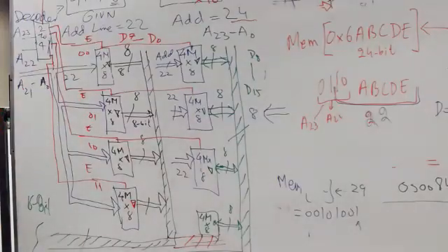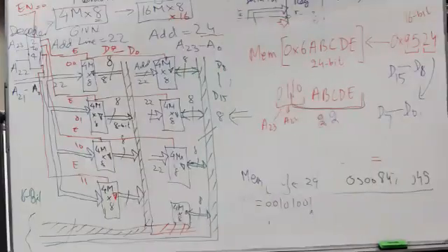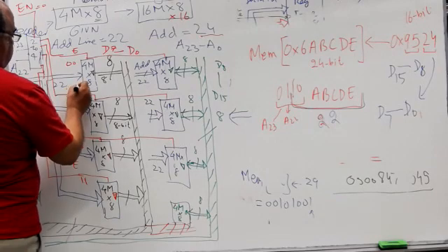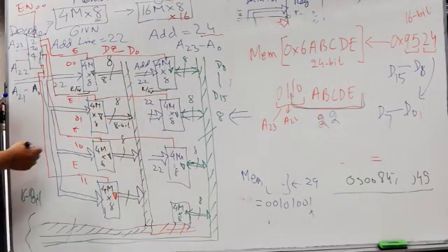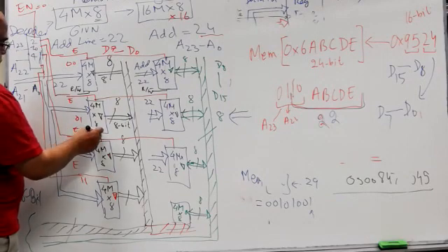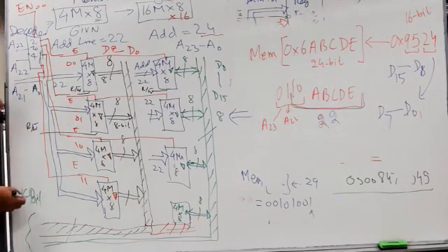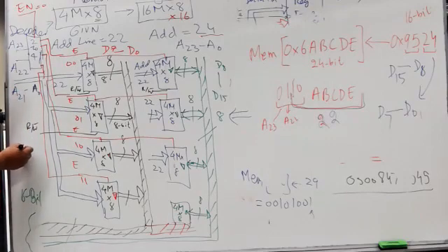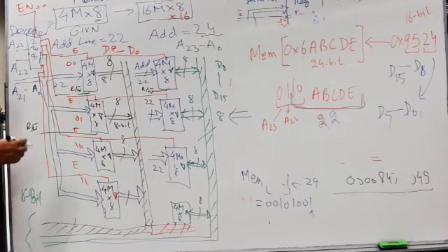One thing common to all of these ICs that I forgot to include is read/write. Because this is RAM, all of them have a read/write signal. Remember whether to read or write, load or store the data. I often don't draw it, I just write read/write going to all the ICs. The processor has only one read/write control that goes to all ICs in the memory.